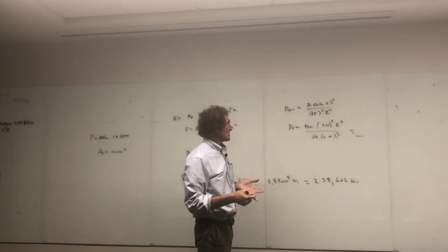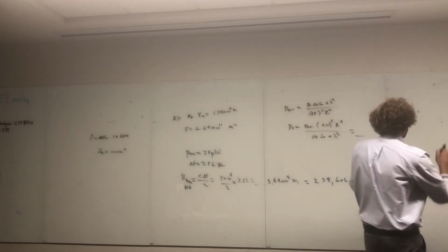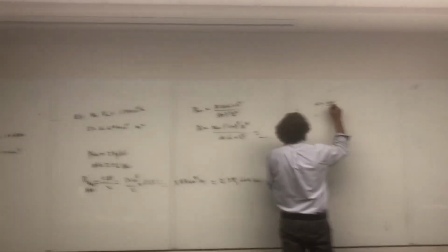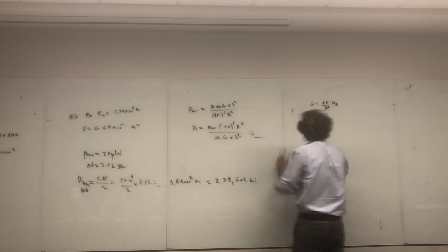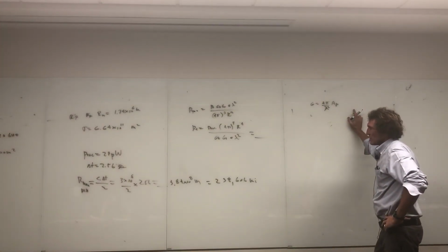I don't know how much power is transmitted. You've got the distance, you've got R, you've got the gains, or I should say the apertures, so you have to change that. You can get the gain by simply saying the gain is equal to 4 pi over lambda squared times the actual aperture. And this is 100, so 4 pi over lambda squared can be the gain that you use in that formula.